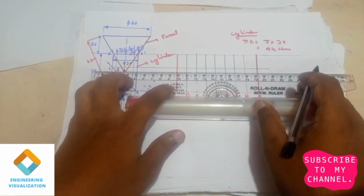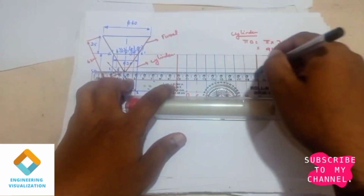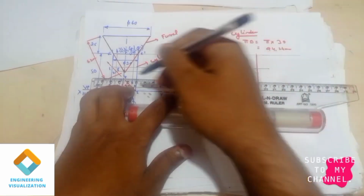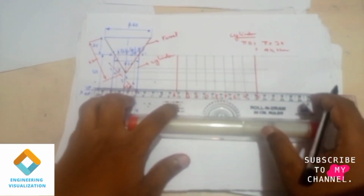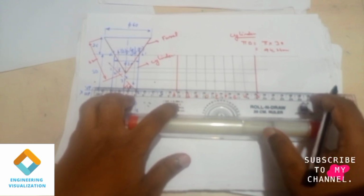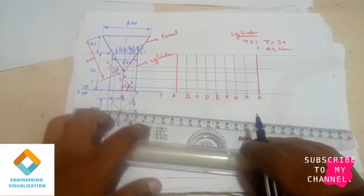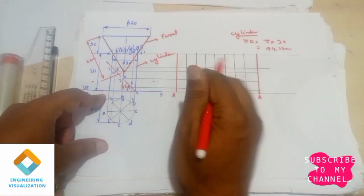Okay, from the point 2 also you do the same thing, and from 3 also the same thing. So this cylinder and prism will be constructed in the same manner, guys, because all the cut points are occurring at these vertical edges. So no need to measure, just draw the projection lines and then now you mark.